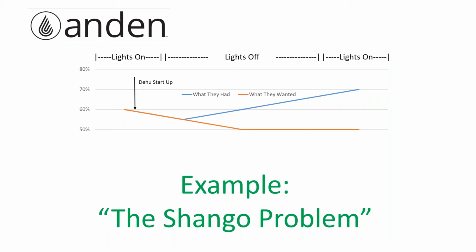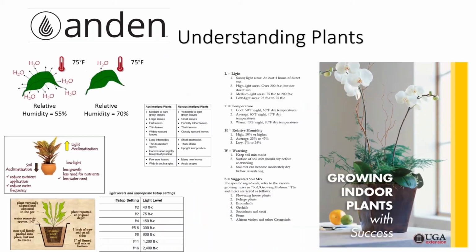And this was something that taught us a lot of valuable lessons as it pertained to controlling a grow inside of this industry. We knew how the plants were going to react. We knew how to change the humidity levels in order to flip the VPD. We understood what we needed to do in order to get them to drink. These were all factors that your average dehumidification company doesn't take into consideration, and it's why you've seen so many people, and maybe yourselves have experienced this as well, who have put the correct amount of dehumidifiers inside of the room for all intents and purposes.